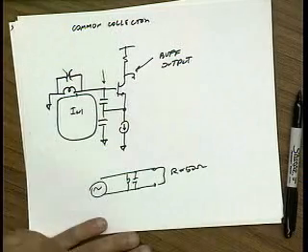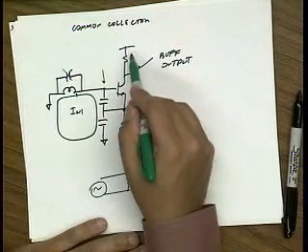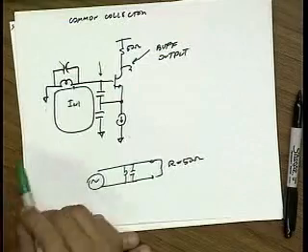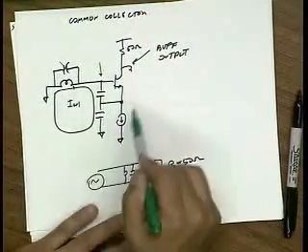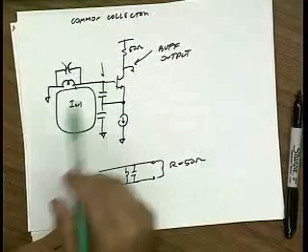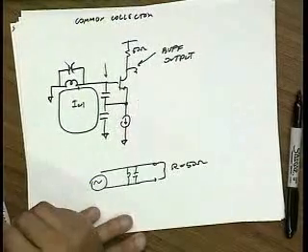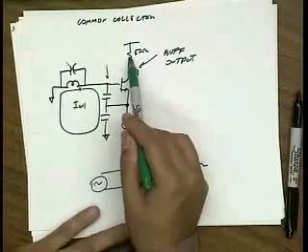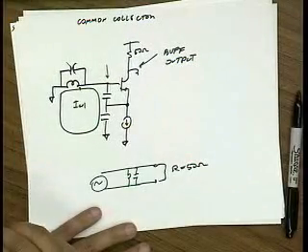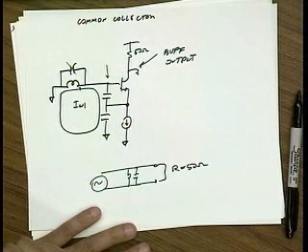onto my tank. But I can put a 50 ohm load here, and as long as this voltage swing is not too big, it's not going to fundamentally change the performance of this. And so I have a buffered output available to me for free. I probably will buffer it more, but this built-in buffering helps. Okay? That makes sense to everybody?